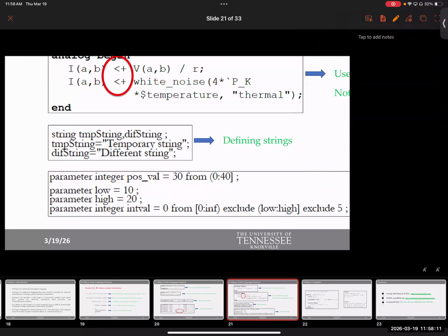All right. There is a reason why you might want to do that. And I'll show you one example why setting these bounds, ranges, is absolutely critical to ensure convergence and to ensure quick convergence. By the way, if you don't provide a range, models could take up any random value, or sometimes because of mistakes, you can pass values that are, okay, imagine you calibrated your device with experiment for a certain range of parameters. You don't want your users to ever go beyond that parameter because the model will give it something. And then you will blame the modeler that, hey, your model is giving me wrong results. Then you have to go debug and say, hey, you didn't pass the right parameters.